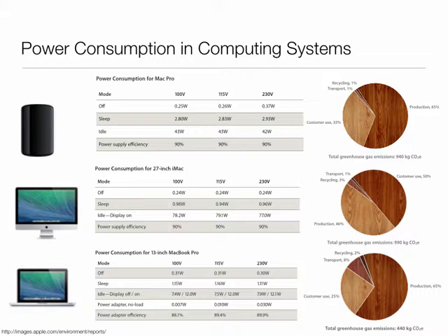So there are all these other additional considerations where a model could come into play, or even things like, let's say I'm making a decision between processing locally versus sending it over and being processed remotely. So I may have to look into energy models of radio versus CPU and consider that. Okay, so there are a variety of different reasons why power models are essential for one to be able to do good power management.